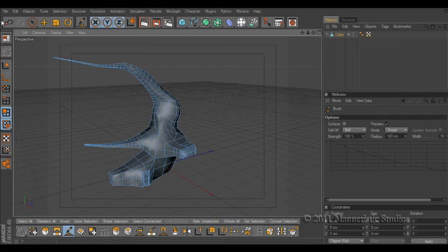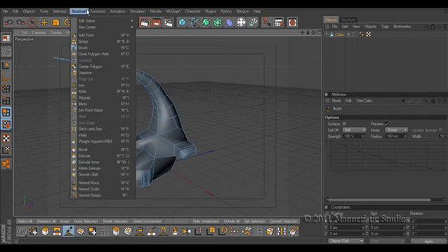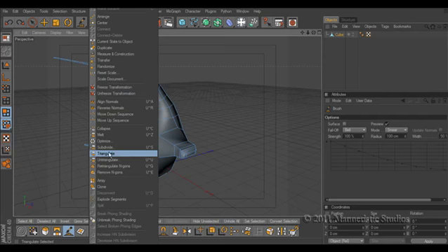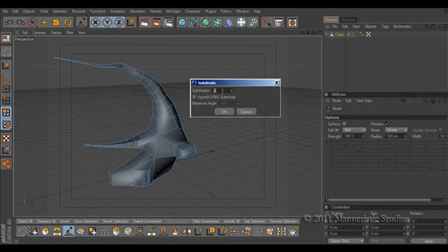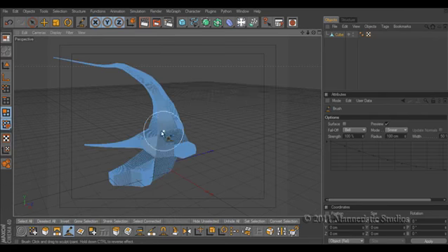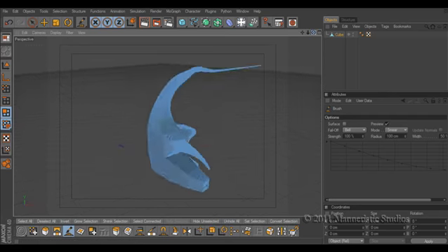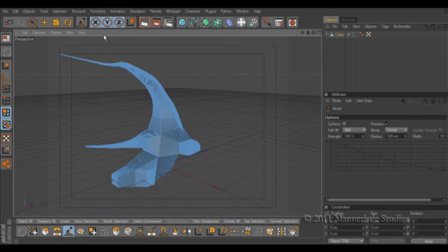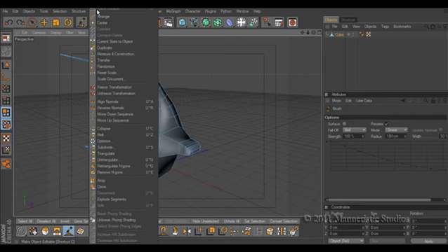Okay. So go back in, undo these steps really quick. Okay, and we're going to go back in and subdivide again. So that was 1. What if we do something like 4? Okay, add 4 and say OK. You see now that it's fully detailed, meaning that for every face, it's going to divide into 4. So there's a lot more detail. And you notice when you add this many polygon faces, your viewport will start to move a little bit slow. So you have to be careful with that. I would say do this in increments between 1 and 2 to get better control over the model.